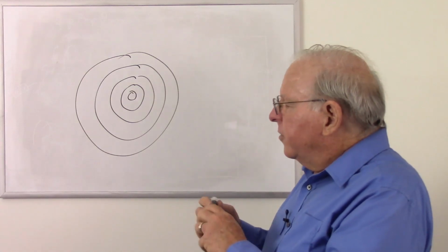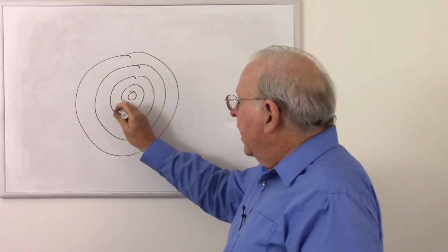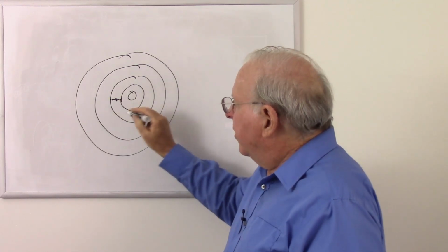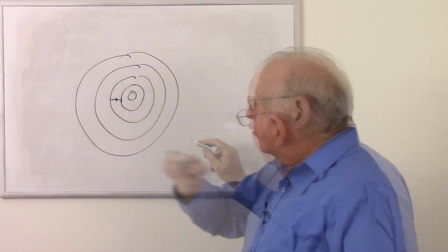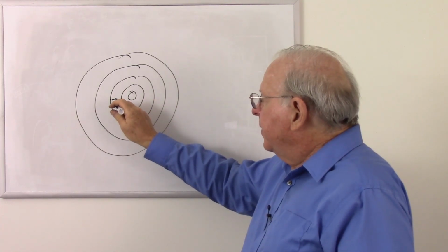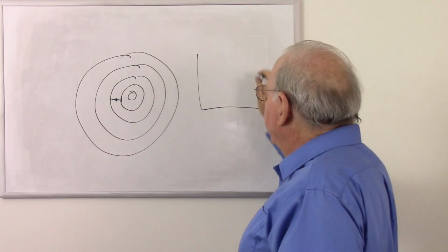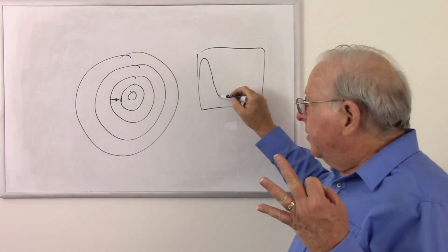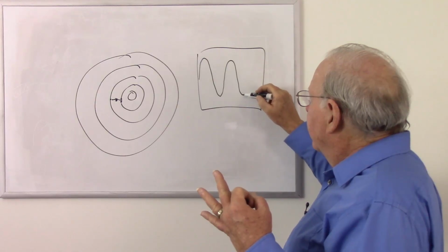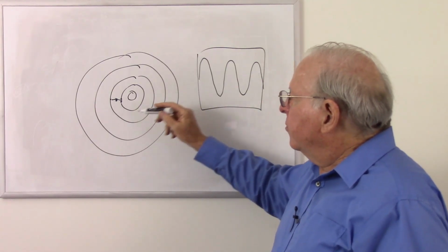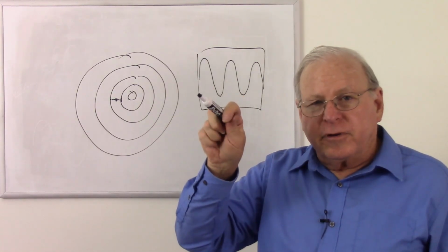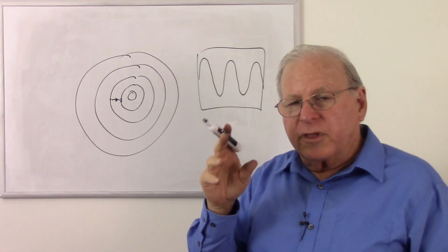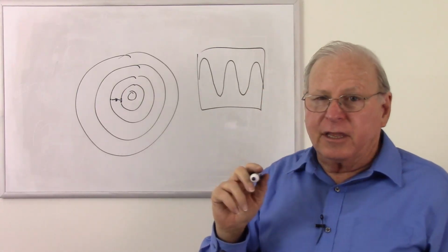So one thing we see here is that there's a gradient. High pressure, medium pressure, low pressure, medium pressure, high pressure. So there's a gradient between these. So if we took a pressure sensor and put it right here and ran that to an oscilloscope, what would we see? We'd see the pressure go up, the pressure go down, the pressure go to a vacuum, if you will, of negative pressure, and go back up. Oh, that looks familiar. This would produce that same signal that I produced by doing that potentiometer, or more realistically, to do it with an oscillator that would actually automatically create these waves.